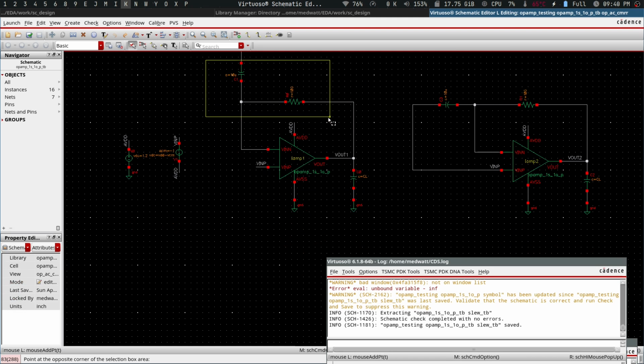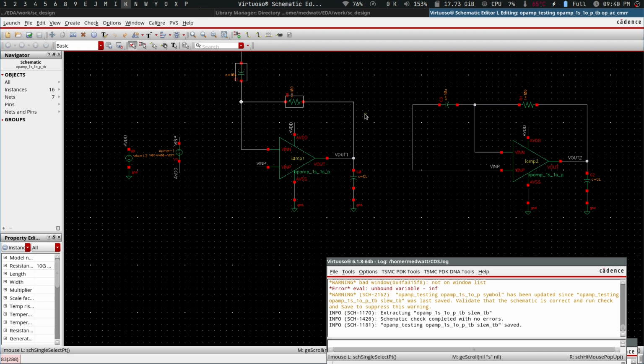So what I'm using here probably is the sort of method that you might use to test your op amp in practice. There might be other methods that might give you more accurate results compared to what you expect from calculations, but these are not methods that you can probably use in practice to test the op amp. So here I'm using a method which is practical to test. This is why I want to point out that the test bench you use to test the AC or the open loop characteristic of the op amp has an impact. So just keep that at the back of your mind.